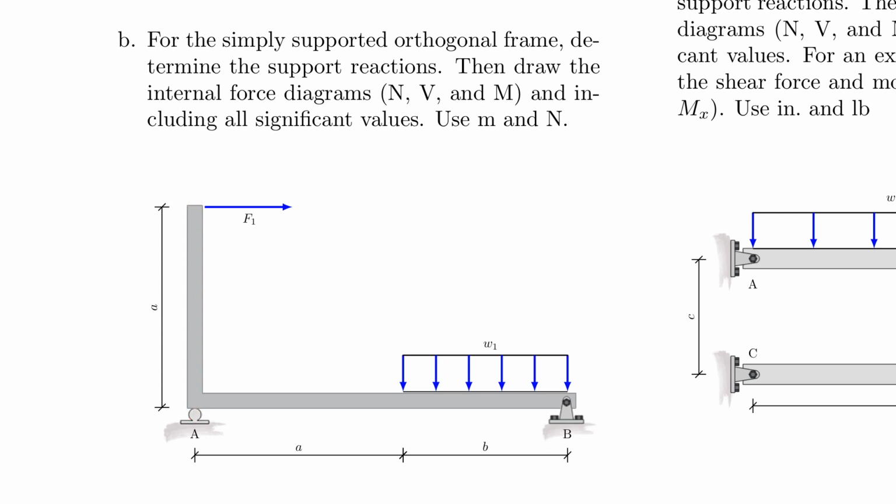And once again, you kind of want to identify where your reference fiber is. For this problem here, the way I would do it is just on the bottom, as I always do, and then I also choose the inside. You could have, for example, also moved this reference fiber to the top just for practice purposes, or you could put this to the outside, then it would pretty much line up with this one. It's up to you, but my personal convention is inside and bottom. That's how I usually do it.